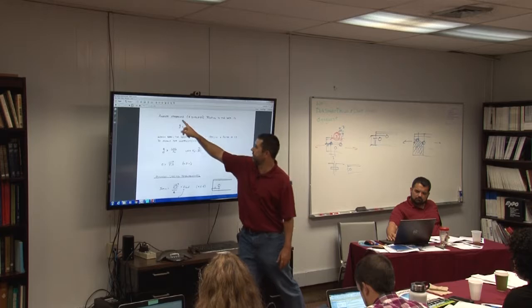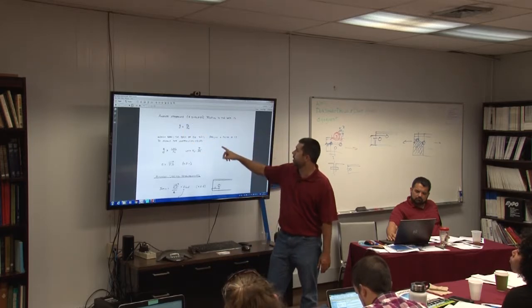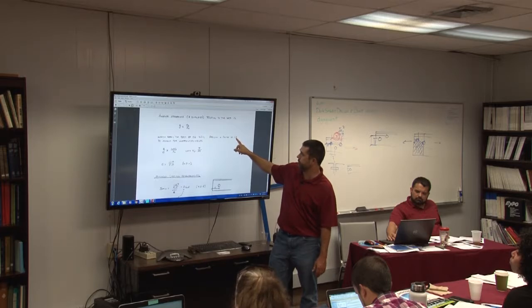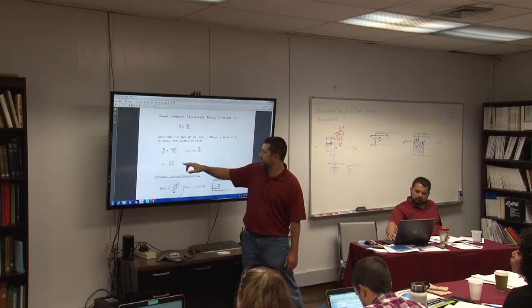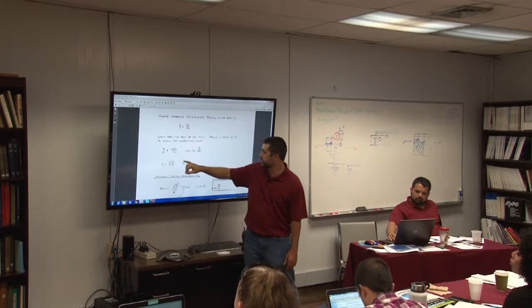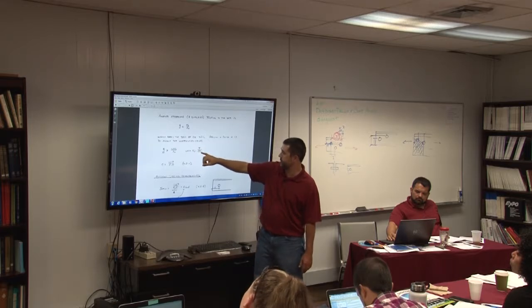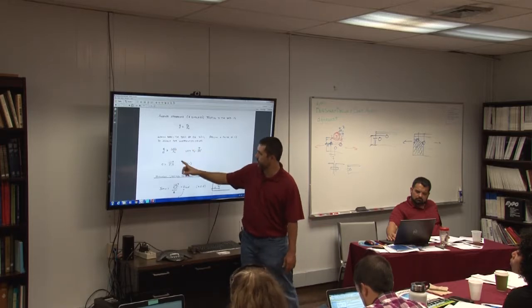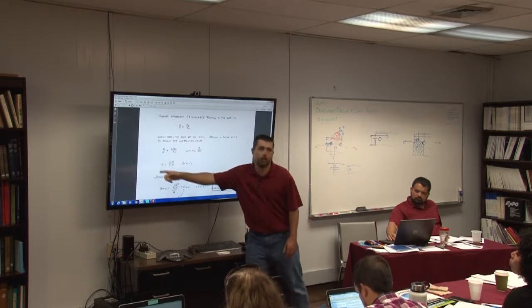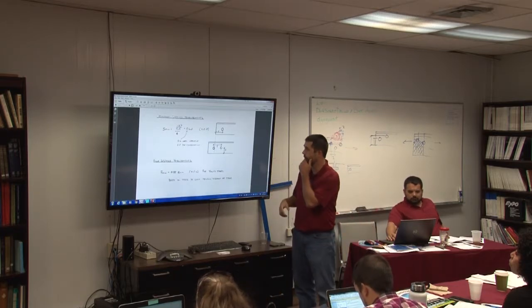This is that simplified line that I showed, which is the basis of equation 451. Applying a factor of 1.2 to account for uncertainty gives this equation for essentially the end distance and related to the bearing stress. If we know that the bearing stress is essentially the load divided by the diameter times the thickness, then you can substitute this in here, and what you end up with is essentially our design equation in the code. So that's kind of where it came from.